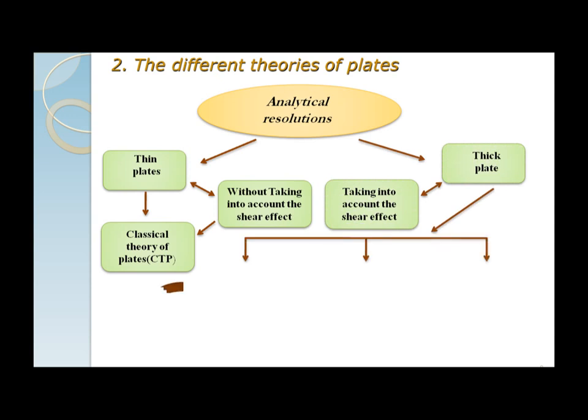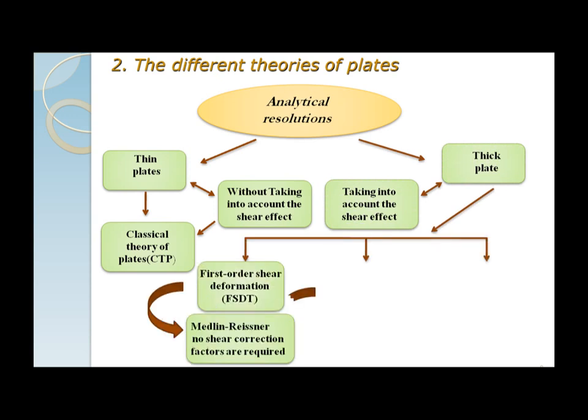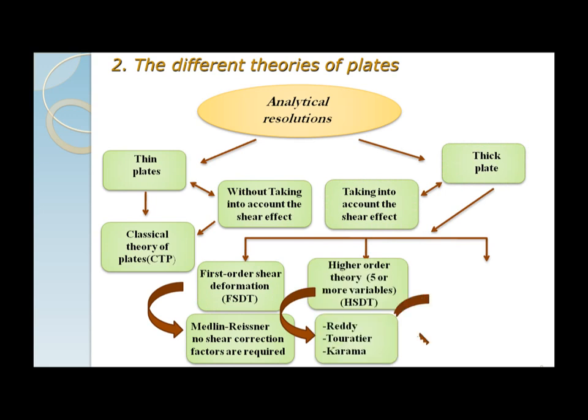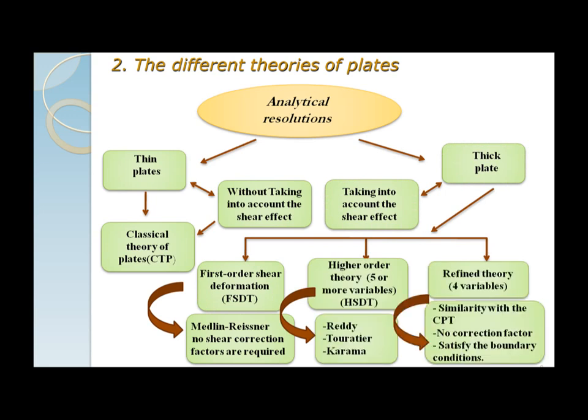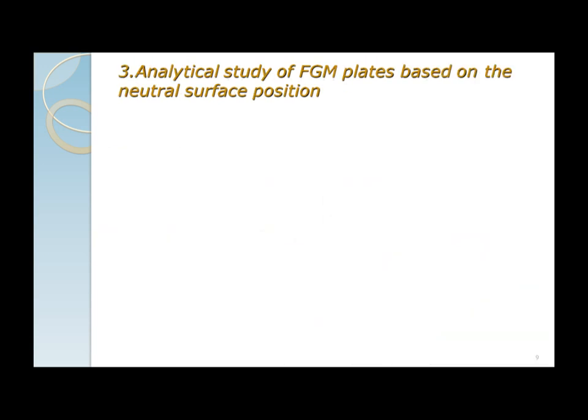For thick plate, we take into account the shear effect. We have the first order shear deformation theory FSDT of Mindlin-Reissner. No shear correction factor is required. High order theory, five or more variables HSDT of Reddy, and refined theory, four variables, similar to the CPT, no correction factor, satisfy the boundary condition.